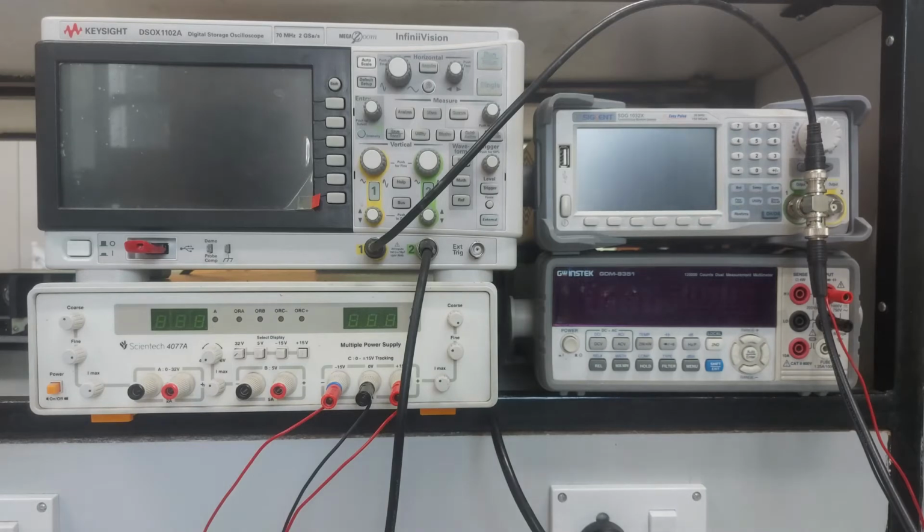It has a voltage gain of the order of 10 to the power 6. This is actually a voltage amplifier; op-amp 741 is a voltage amplifier. Suppose you give 1 microvolt as input, you will get 1 volt at the output. That much gain it can provide, in the order of mega. But it has a finite bandwidth also, not infinite, though the bandwidth is very large.